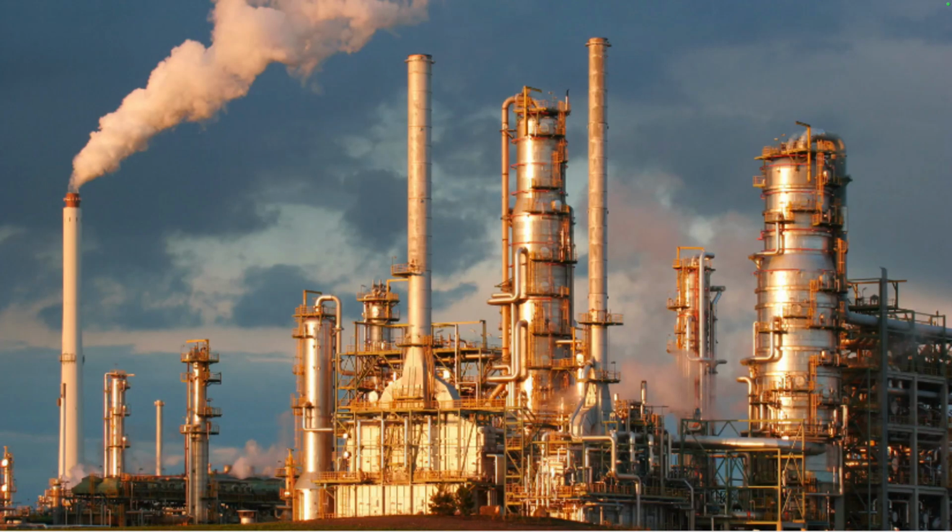You may have seen these towers before. They're for refining petroleum. The petroleum is separated into different products based on their boiling point, with the highest boiling point at the bottom of the tower and the lowest boiling point at the top. For example, asphalt has a high boiling point, so it would be produced at the bottom. Diesel oil would be higher up, heating oil would be higher, jet fuel would be higher, gasoline would be higher, and other kinds of gases with lower boiling points would be higher on the towers. So the lower the boiling point, the higher it is on the tower.